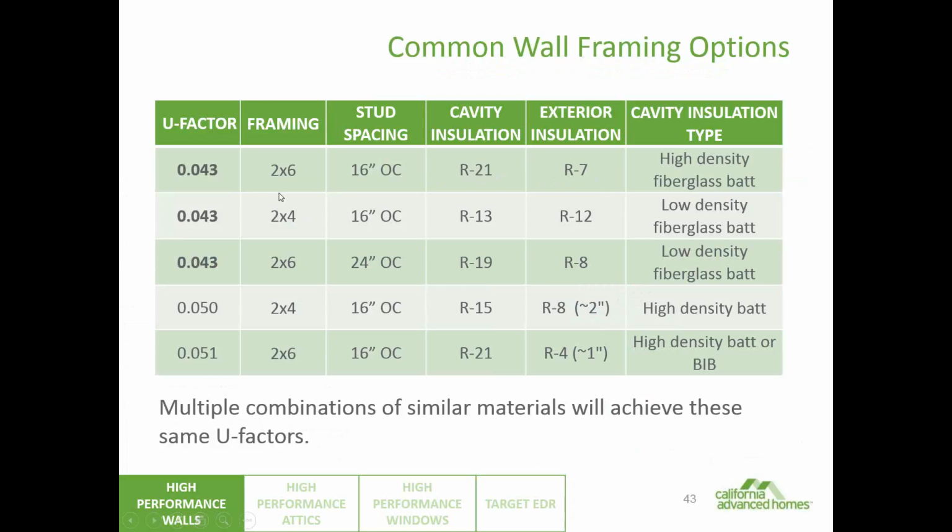You can still do it in a 2x4 wall, 16 on center, R13, but now you've got an R12 on the outside, so now you're talking like 3 inches of foam on the outside. I think that's, in most people's books, unrealistic. Although even the R7 or the R8 may also be unrealistic to people, at least where their thinking is now. I think it's doable. I've built that way. You can get there, but this is just some of the assemblies.